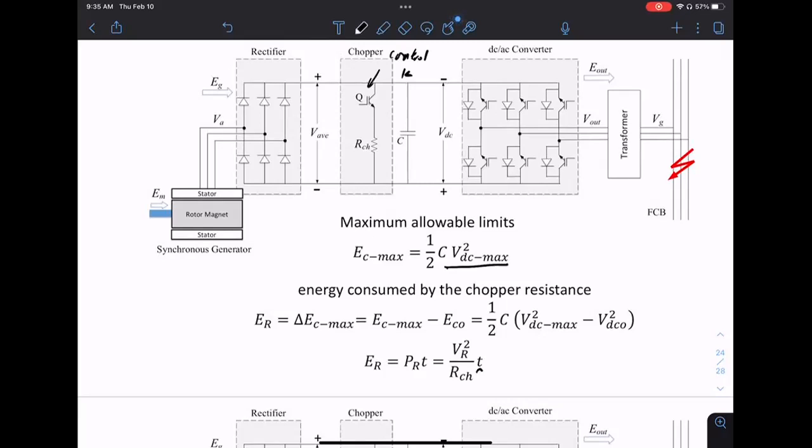In real time, of course, this is an on-off switch. Sometimes you see the entire resistor, sometimes this is open. But we're going to assume it switches fast enough, much faster than the time constant of this circuit, such that it appears as an effective resistance. That's important. We're going to assume the switching will be fast enough.